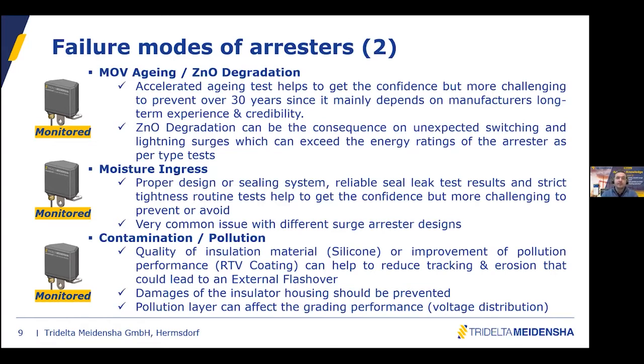There are plenty of reasons for having MOV aging. Under normal condition, MOV zinc oxide blocks do not age. This is tested according to accelerated aging test, and all specialists, all MOV manufacturers will tell you that an MOV block does not age under normal condition.